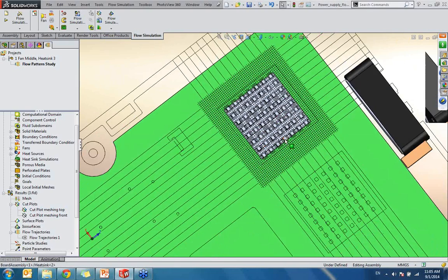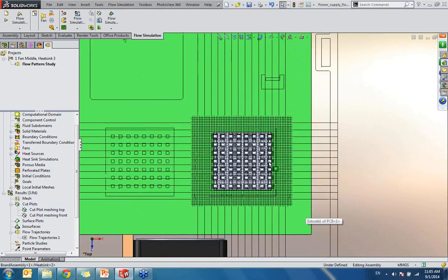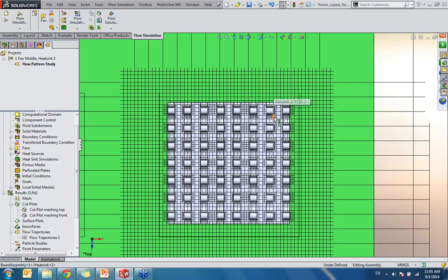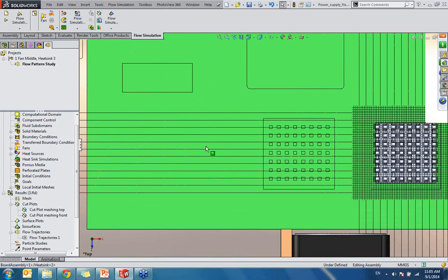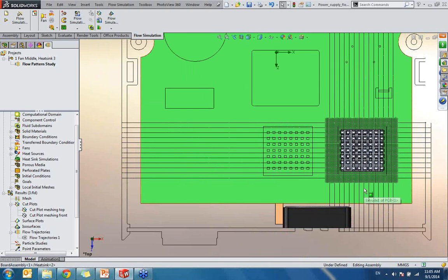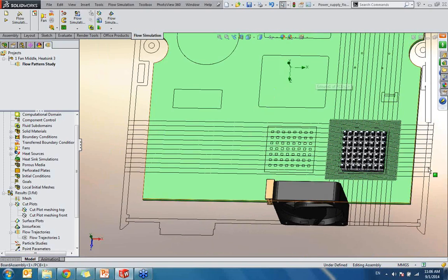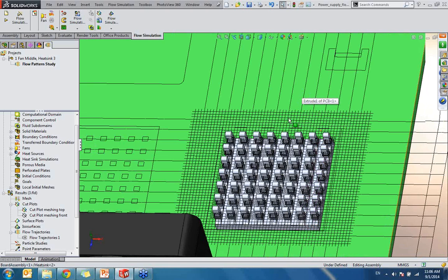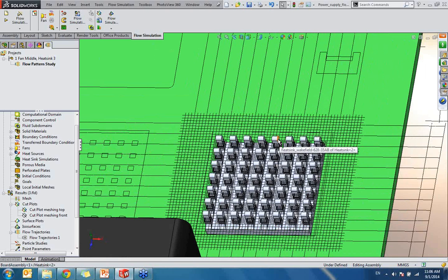Okay, you see that. Now you will see the focus on the study: the meshing is only in this boundary. The other areas outside this boundary didn't have any meshing. It means that there is no solve or calculation in all this area. So the problem comes out already. If they didn't cover all the areas, how do they know the air that flows through this area, like the air that flows in this direction to this heat sink?